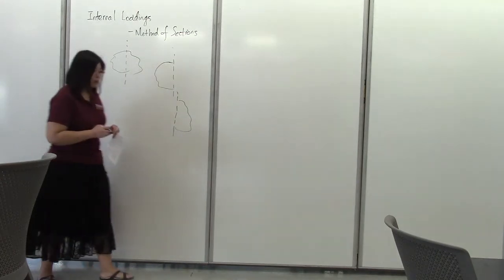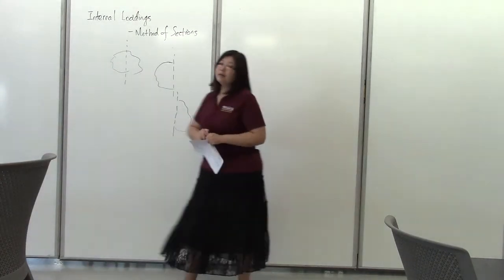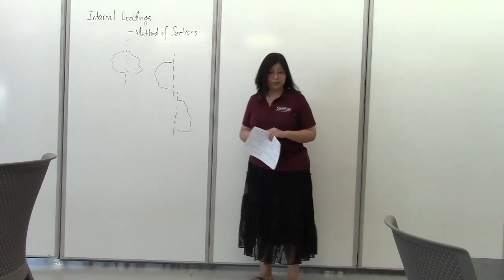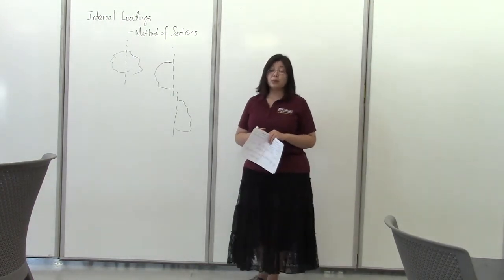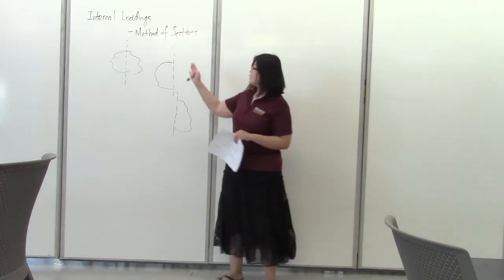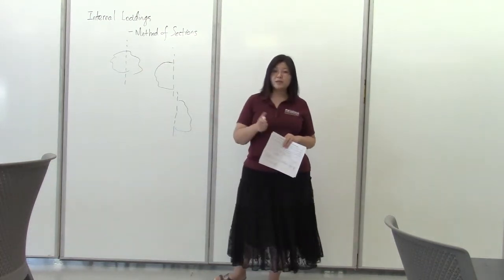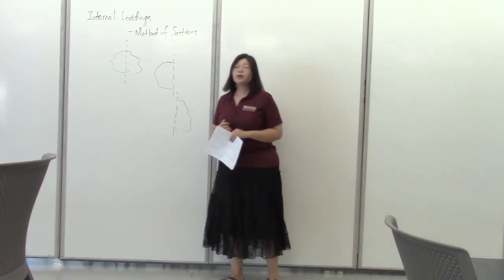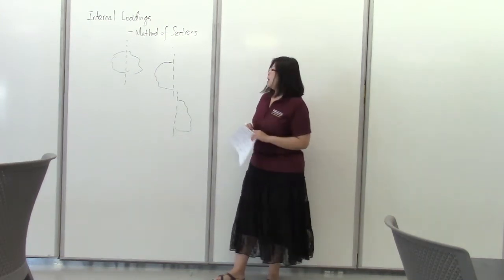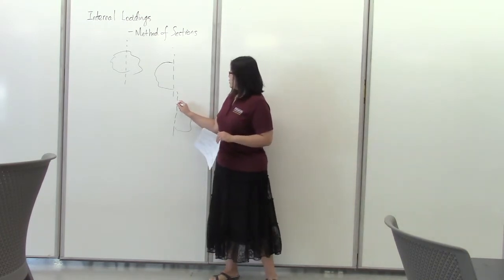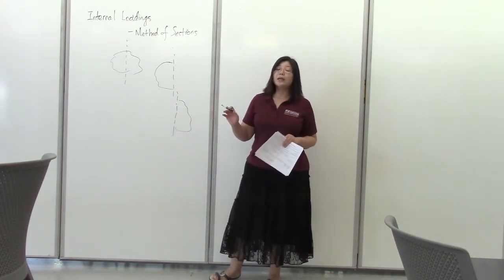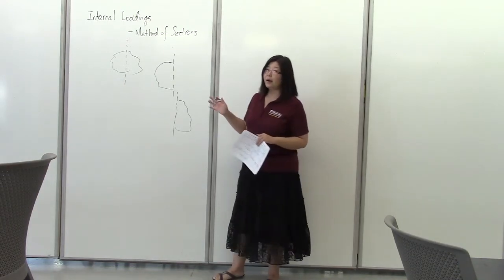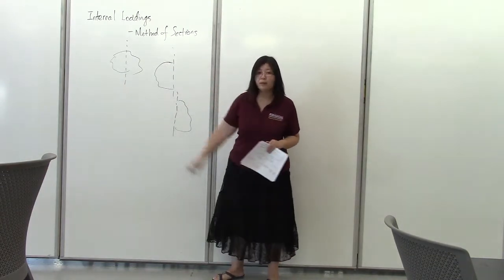Okay? For 2D problems, in general, on this cut section we have different types of internal loadings. We could have a normal force that is normal to the cut section. We can have a shear force that is tangential to the cut section. We could have a bending moment. We could also have a torque. And the most important thing to note here is that you should only include externally applied loadings that are actually applied on this part of the body.